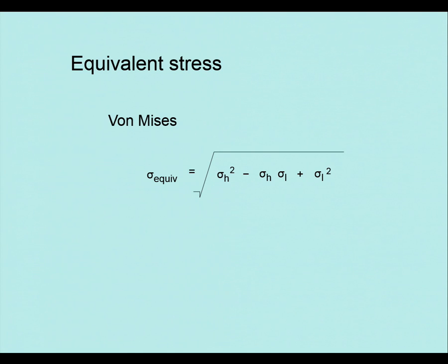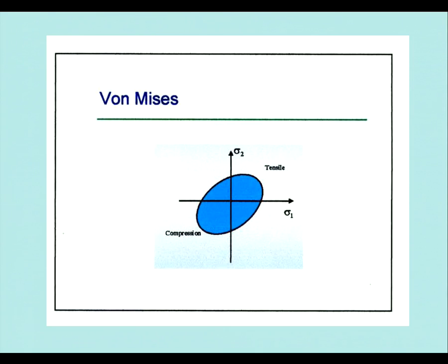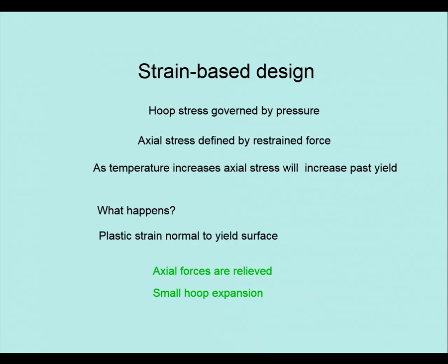And the one we need, there is actually a shear force in this, but you notice in none of the formulas have we taken shear force into account. That's the shear force that way through the pipe. We don't, because it's so small. So you can use this formula, and basically you get the von Mises ellipse, and just like that failure ellipse for the buckling, you can now take this.